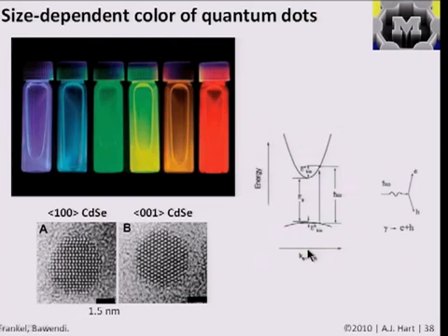And a couple things are important here. One is that you will only get light emitted across the basic band gap of the material, not from a higher state to the ground state. So if you excite the electron to somewhere up here, for example, it most likely will decay non-radiatively, will release heat or scatter in other ways until it reaches the lower tip of this band, and then it will cross the band, and then it will emit a photon with energy like so.